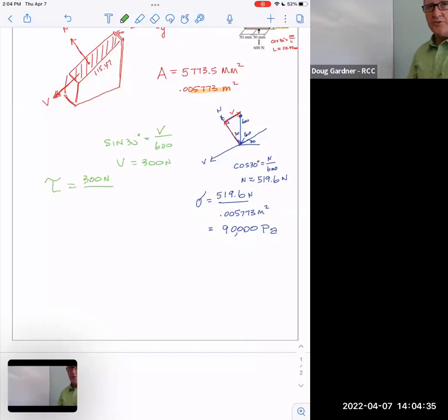So shear and normal are just forces. It's just a question of direction, ripping apart or sliding along, divided by the same exact area, newtons per square meter, and I get 51,962 pascals.